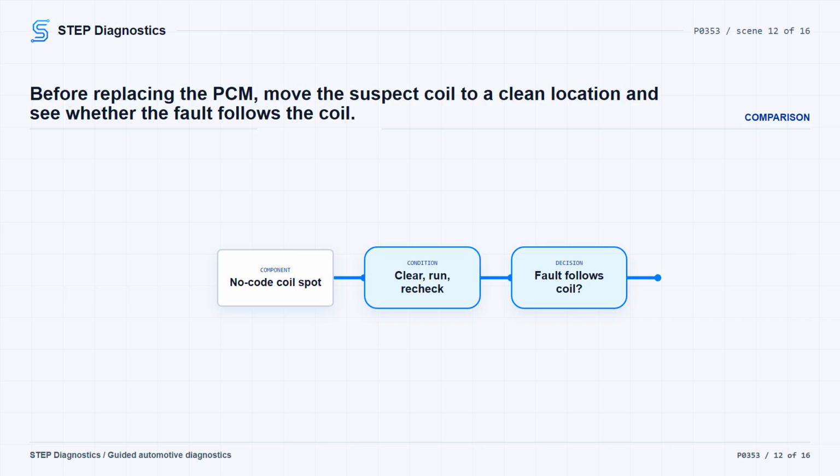Turn the ignition on, erase the codes, then start and run the engine for up to 1 minute. If the engine will not start, crank the engine 3 times for 10 seconds. Read the codes again. If a correlating fault sets for the new coil location, replace the ignition coil and replace and program the PCM, then verify the repair and confirm the code stays gone. If a correlating fault does not set at the new coil location, continue with the related connection checks.